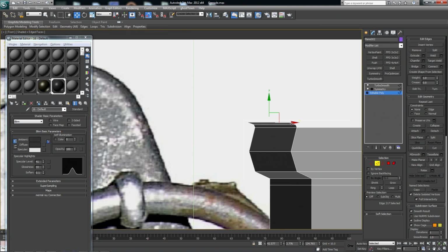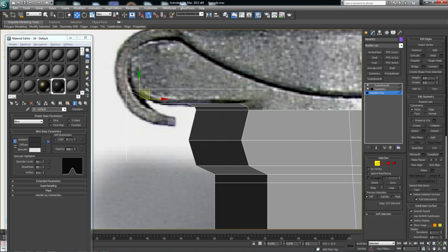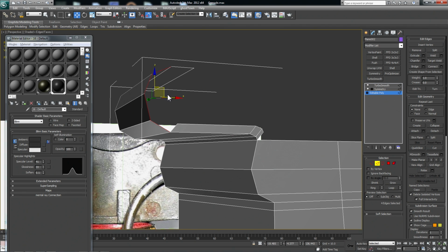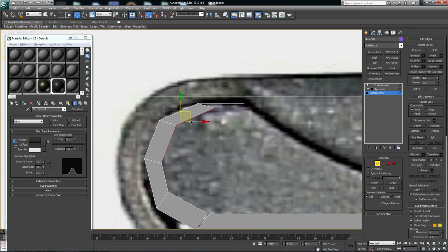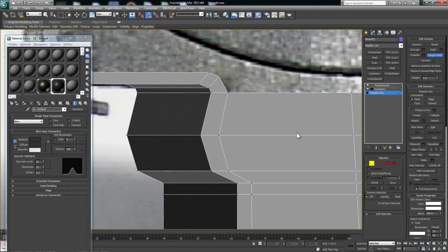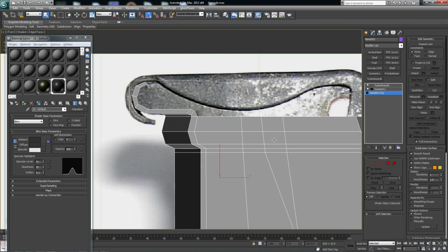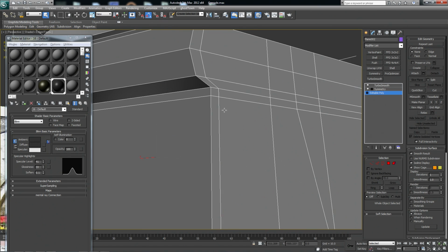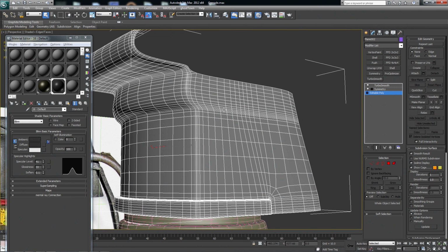Now I'll take this bottom edge and shift drag it around at even increments to form the round lip of the grenade. Next, I'll manually drag out a border edge from the front view, and I'll add a swift loop below and use target weld to connect the new edge loop to our base. This gives us a nice clean supporting edge that flows in the same direction as our lip piece, which will make for a nicer, non-pinchy subdivision.